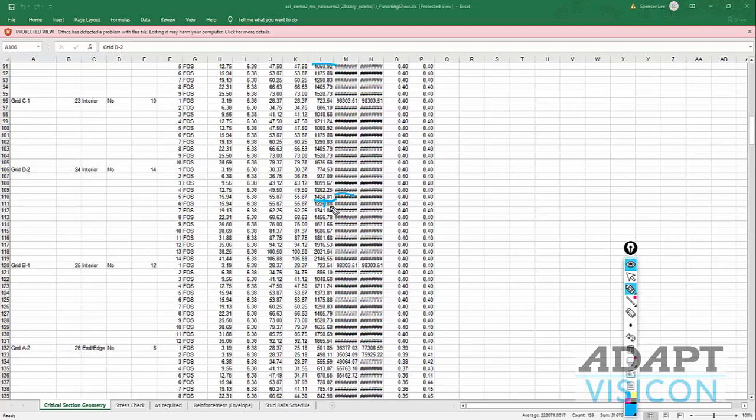That indicates that is the location where we transition from a rectilinear to an octagonally shaped section. And then there's additional checks made beyond that, all the way from 6 through 14, which are required in order to get the stress less than 2 square root of f prime c. And that affects the amount of reinforcement being added to this particular design.